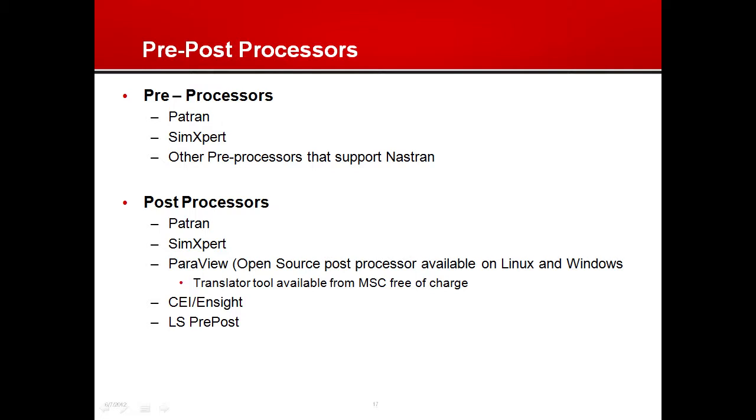Post-processors, there's quite a few available to you. Again, our standard tools, Patran and SimExpert, are available to you and do post-process. So those are available, but then there's some other shareware. ParaView is a free code that does a nice job for presentation. CEI Ensight is an extremely powerful tool and does fantastic presentations. We use it quite often. And LS-PrePost, which is a post-processor created by LSTC, makers of LS-DYNA.